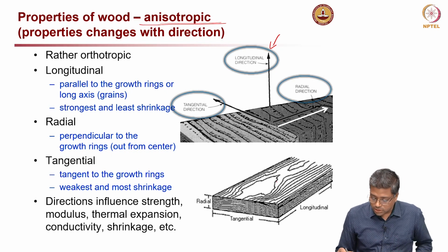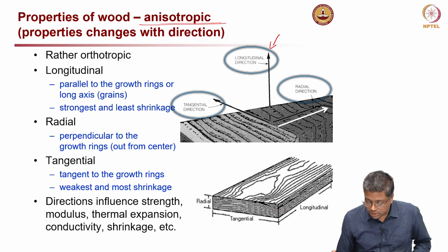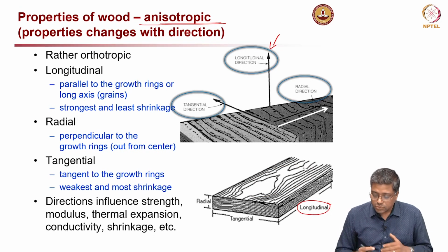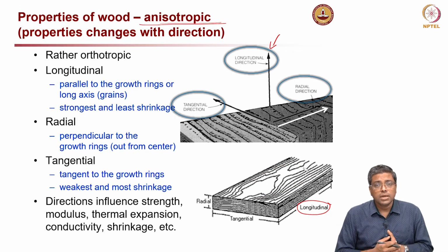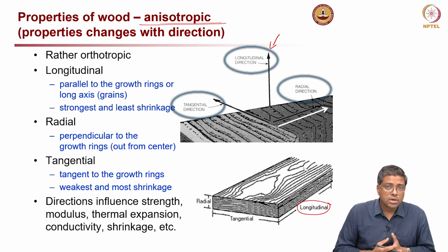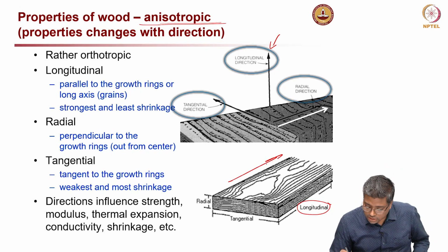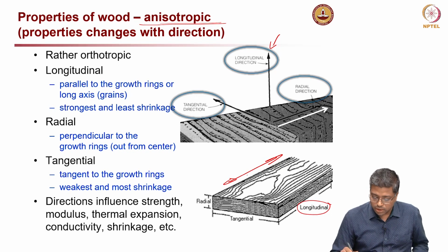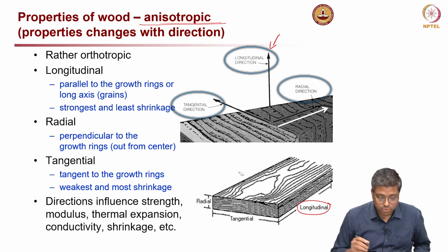Okay. So, look at the picture on the bottom right, you can see this is the longitudinal direction I am talking about, and these are all the grains you can see, and along the grains they do not shrink much, or shrinkage in this direction is very minimal.